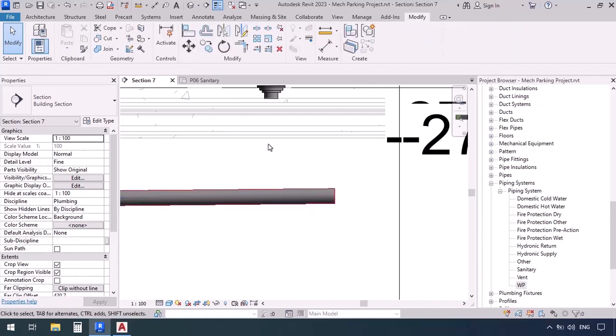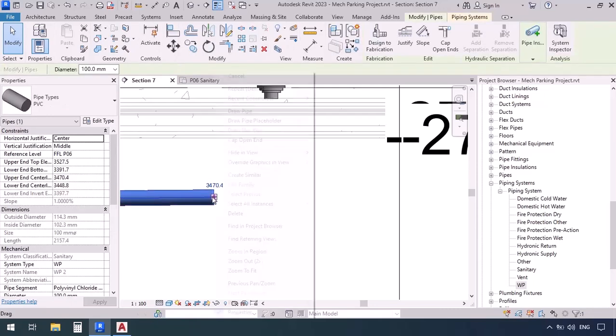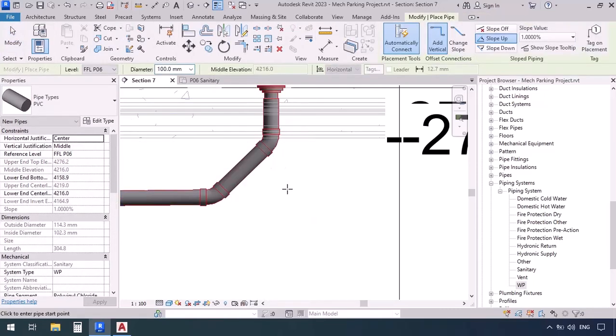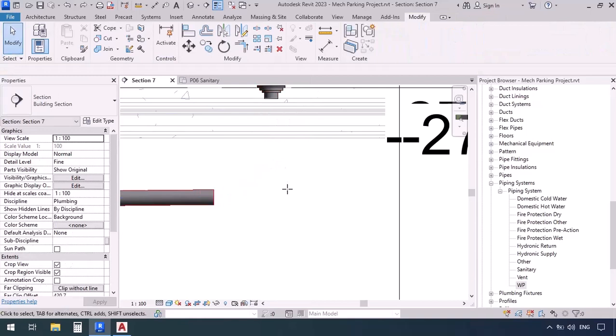Or you could just go to Modify and then click on Split Element. Then the pointer turns into a cutter, so we're going to click to cut the pipe. And now we're going to select this cut part and then delete it. And then to continue, we're going to right click and draw pipe, then continue at a 45 degree and finish. Now I'm going to press Ctrl Z. So now we're going to get a conclusion.